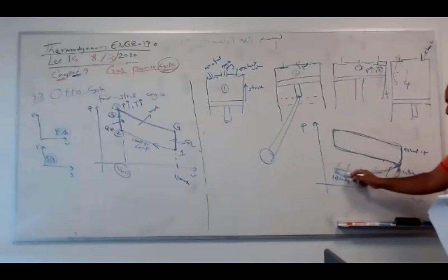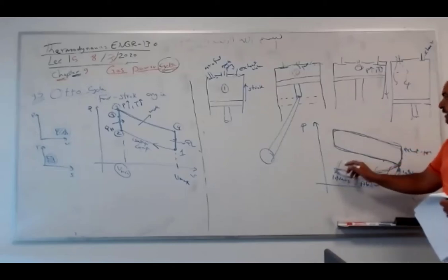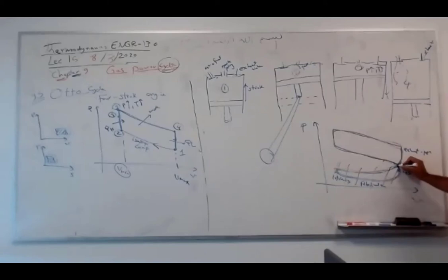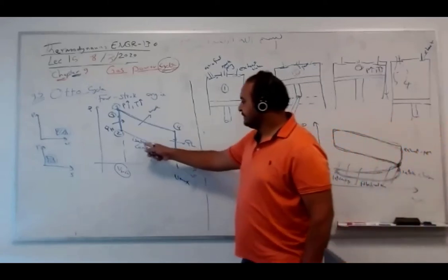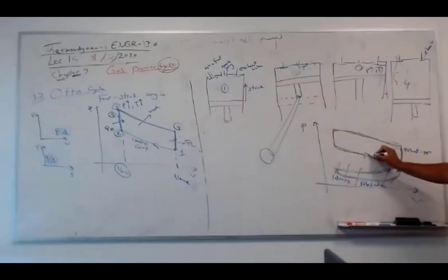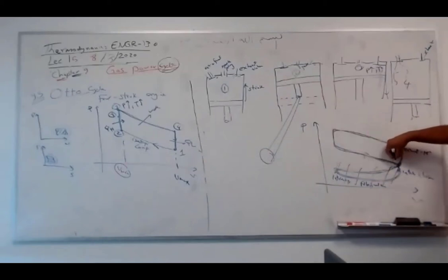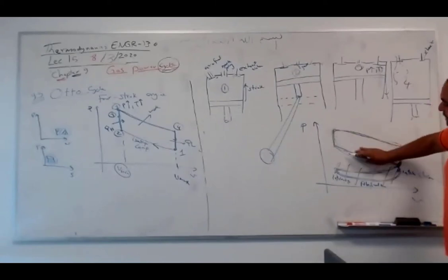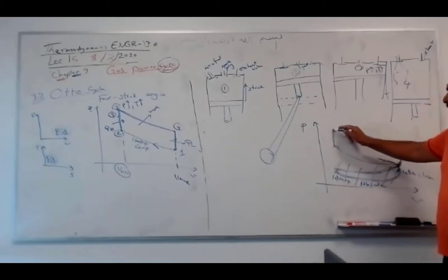From this point to that point, exhaust was open. Exhaust valve was open. So just let every smoke go outside. We don't care about this part. We said we're gonna start here and everything is closed. Compression, isentropic compression. The first stroke looks like 2-stroke assumptions. Isentropic, it's a little bit slanted with high slope, something like this. Isentropic compression. Then we have heat addition at constant volume. In reality it was curved like this, but we assume constant volume.